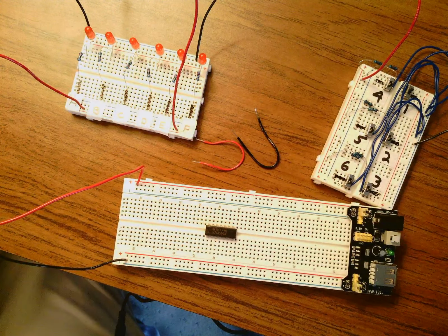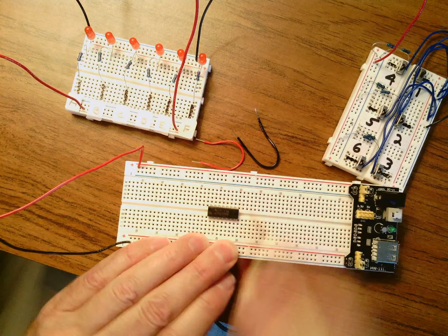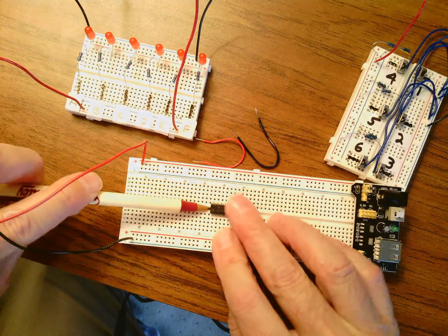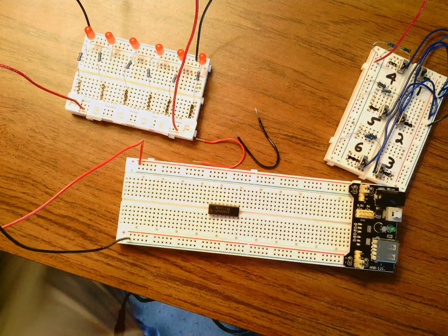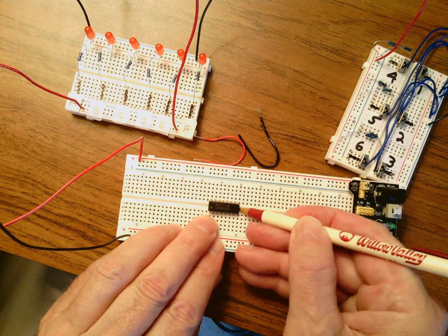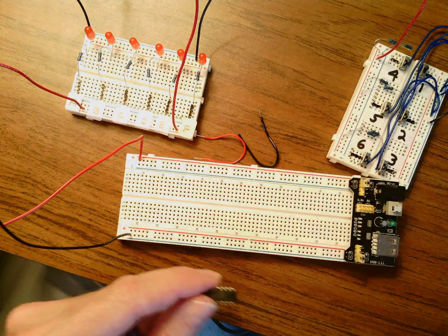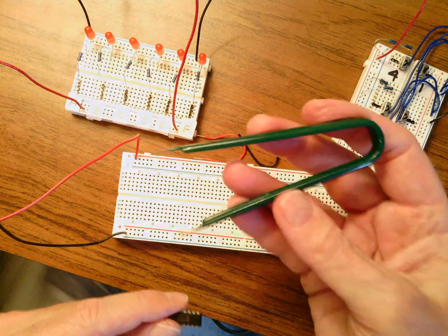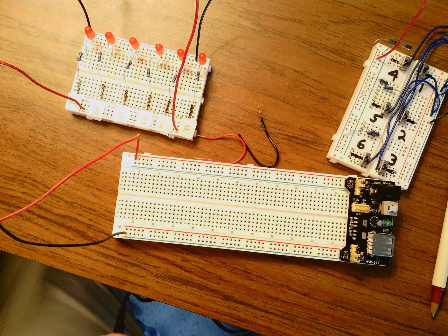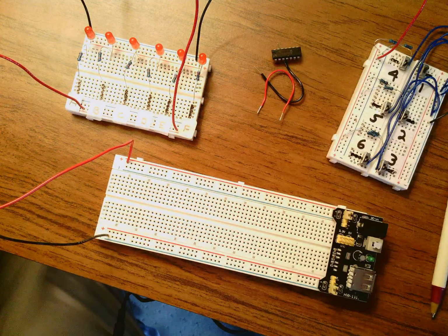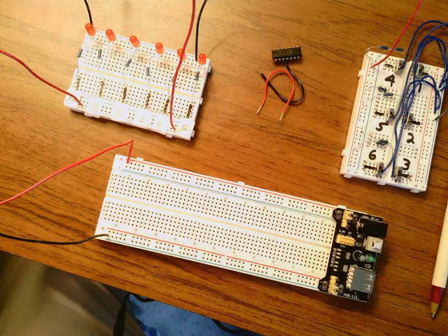In my face-to-face class, what I let students do is this. Engineers do this all the time. I'll let them take a pen or a pencil and pry this side just a little bit, and then take this side and pry it just a little bit, like that. Then go this side and pry it just a little bit so you don't bend it too much, and pop it out. I'll allow you to remove your chips using a pen or a pencil if you do it the way I just showed you. Otherwise, use the extractor. And that finishes up our first laboratory exercise, and hopefully, again, it'll familiarize you with everything we have here.